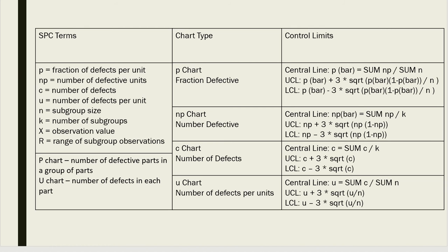When it comes to SPC, there is a wide range of charts that illustrate different aspects of the process. When it comes to the control limits of a specific system or process, the upper limit and lower limit set the standards within which the outcome should lie. These limits are found by collecting a sample, usually of 30 or more, and calculating the standard deviation and average.